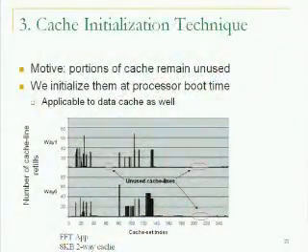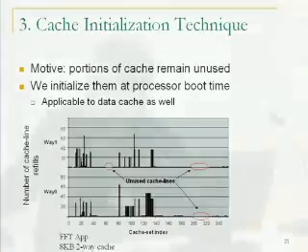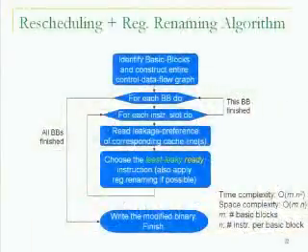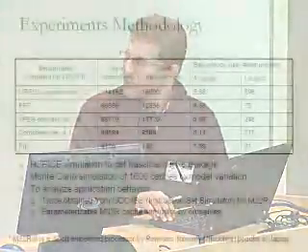And these are some results from running one application, say here the FFT application. This is on a two-way cache, an 8 kilobyte cache. The vertical axis shows the number of cache refill operations. So in these parts, you have 0 cache refills, meaning that part of the cache is never used, so you can initialize all of them. This is the algorithm. Let me again skip it. It's simply a list scheduling algorithm.